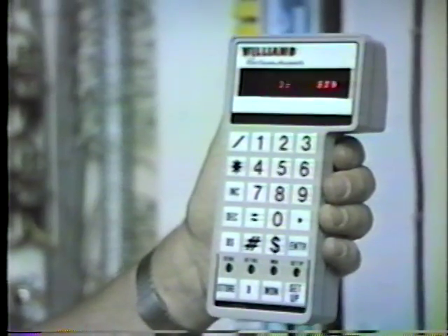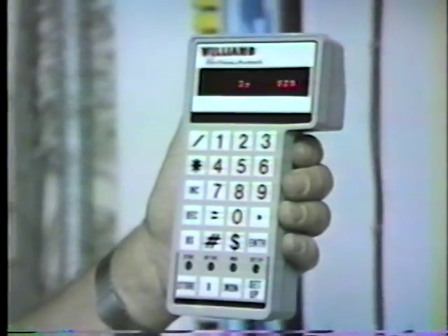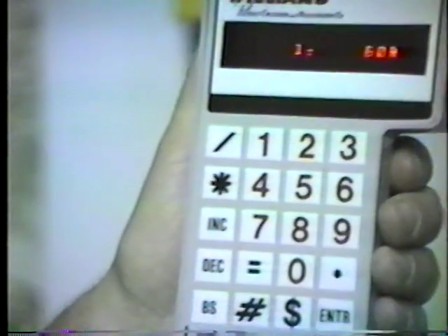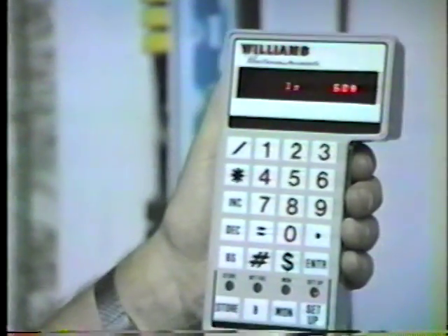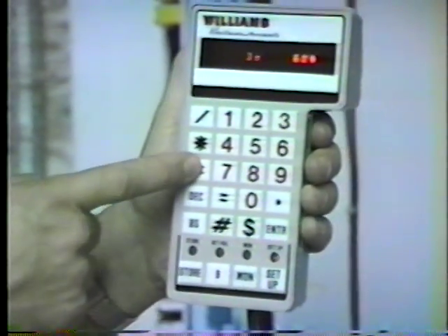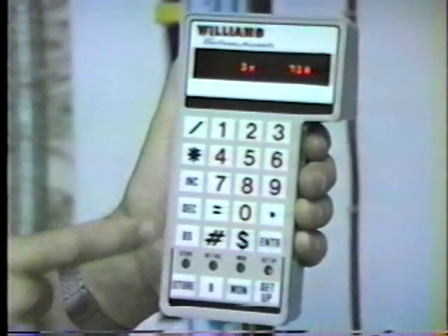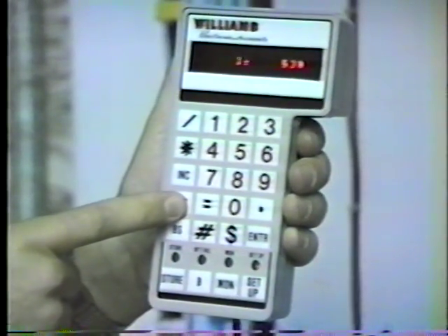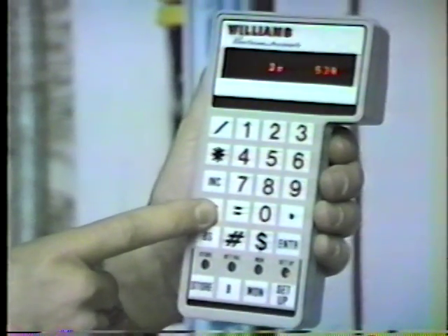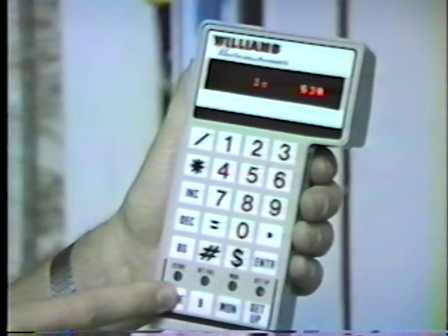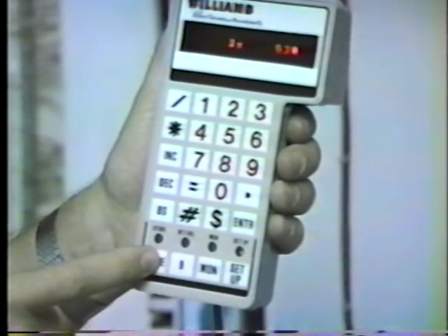The first variable in the setup, variable number 1, is the minimum operating mill speed. You can see that it's set for 60% of scale. That can be changed by pushing the increase button or lowered by pushing the decrease button. Whatever number you want to leave it at, for instance 53%, you then push the store button. Until you push store, you haven't really changed the number that the computer is using.